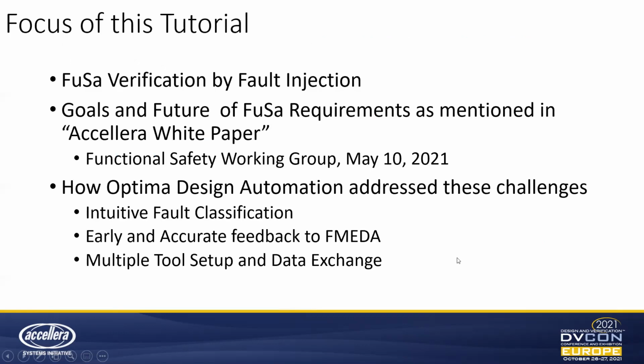So the focus of this tutorial is FuSa verification by fault injection, and the goals and future requirements as mentioned in the Accellera white paper I just mentioned, and how Optima Design Automation addresses this challenge. The challenges are intuitive fault classification, early and accurate feedback to the FMEDA, and multiple tool setup and data exchange.